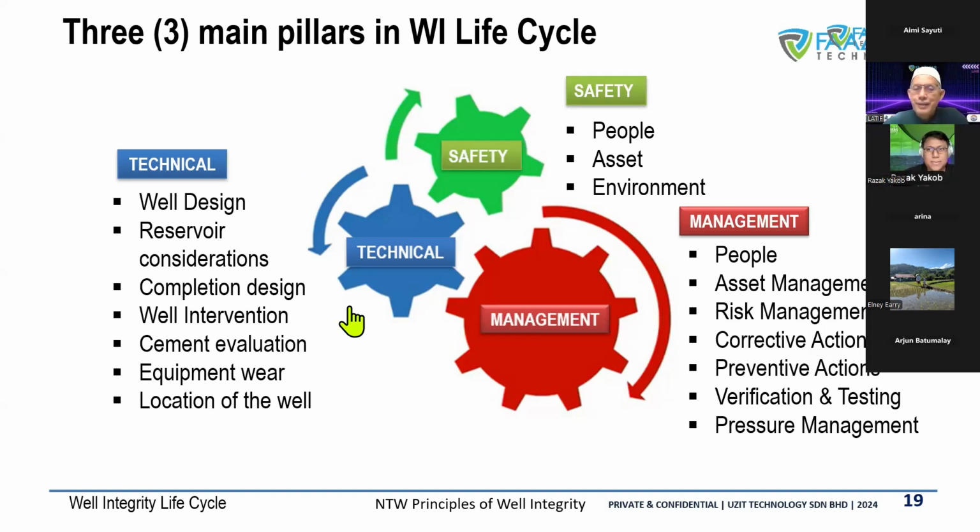Yeah, thank you. Just to summarize again: when we talk about well integrity, we have a few phases. For example, you have a drilling phase where you drill a well. You need to have well integrity, the two barriers. And you drill with the BOP, with the cemented casing, with open hole, and you may have losses. So your barrier is always around the cemented casing and the BOP. And the hydrostatic, like I mentioned, can be temporary because there's no mechanical support, so it's not considered a barrier. But for me, I consider it a temporary barrier, which is part and parcel of managing the barrier that we need to control.